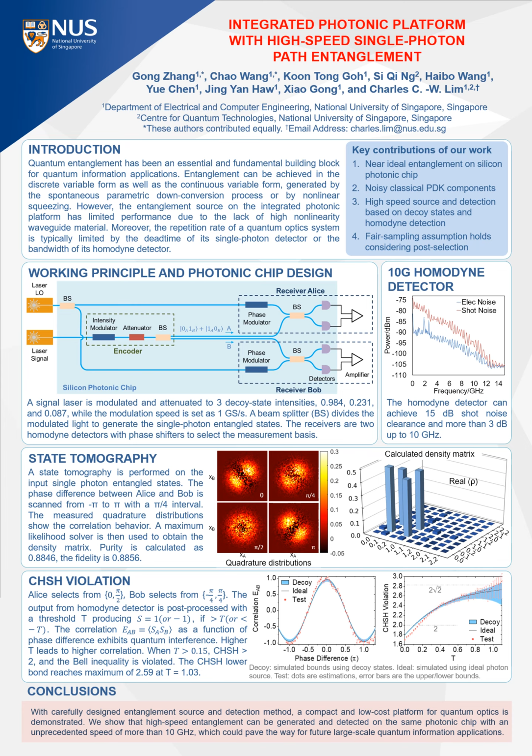For the key contributions of our work, in our scheme, we demonstrated near ideal entanglement on chip using only the noisy PDK components that are not designed for quantum but for classical communication applications. A single photon source and low temperature detector are not required. Here we combine the discrete variable with continuous variable.